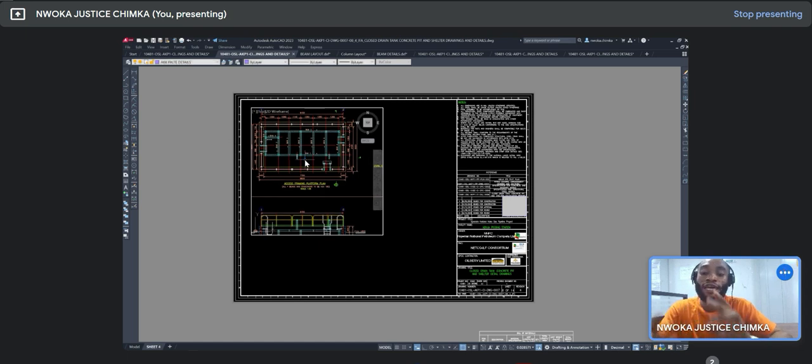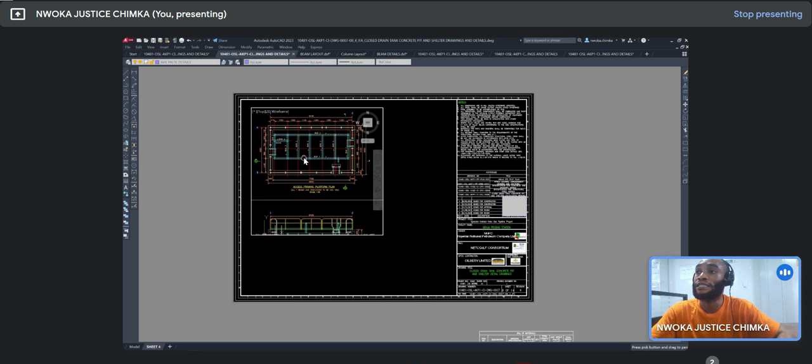So always put SP. Once you type Z enter 1 over, you now put in your scale value, and then if you don't put SP, it will not work. So always put SP at the last point, and then press enter. Then you have just zoomed this drawing to this place by using that scale of 1:35, and then you pan your drawing and place it directly on the place where it is. You can see that right now.